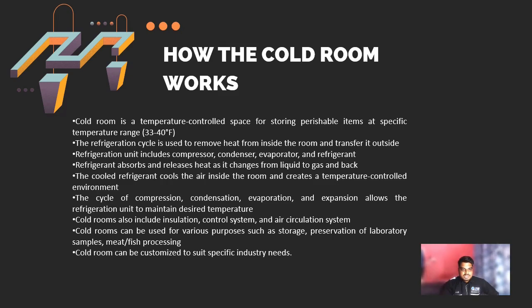Refrigerant absorbs and releases heat as it changes from liquid to gas and back. Refrigerant cools the air inside the room and creates a temperature controlled environment. The cycle of compression, condensation, evaporation, and expansion allows the refrigerant unit to maintain the desired temperature. The cold room also includes insulation, a control system, and an air circulation system.